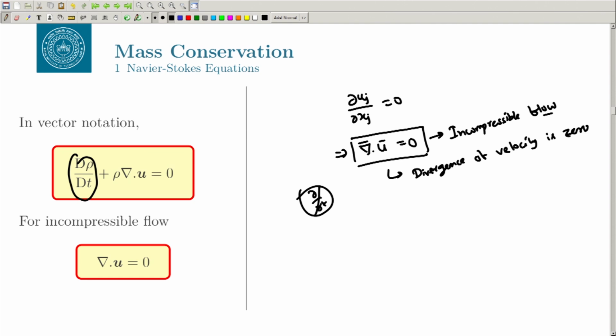So, that is basically giving you the dynamics of the change of the density, right. Because of that you have to do something special, because in the incompressible flow, even if you consider the density to be constant, you have u, v, w and p, right. But the equations that you have are the continuity or the mass conservation, and then you have 3 momentum equations. Okay. So, 3 momentum equations we are going to derive, there is no energy conservation for the incompressible flow.